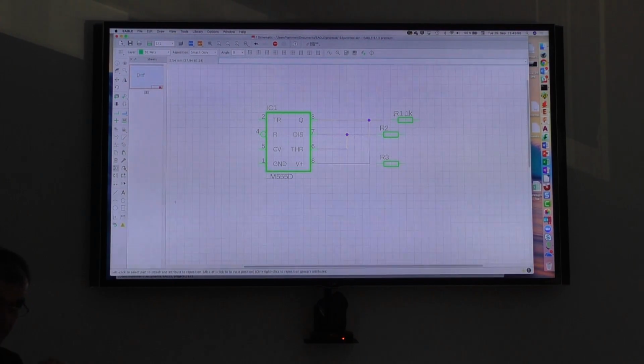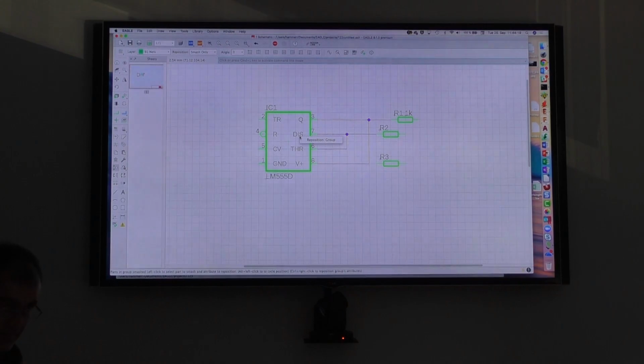If I were to do this with a group, there are two options. I use control, now it's command on Mac systems, control in your systems, and do a right click. And you see all the texts have got an origin, and so they are editable or changeable. And you could also simply do a right click, and then you get a context menu. There is reposition group. We have already done this, but that's also possible.